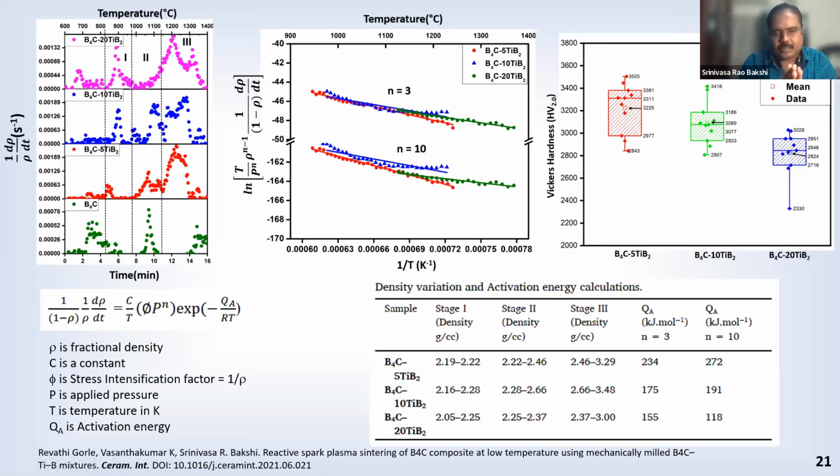So actually, the whole reaction happens in 4 seconds, and the melting happens, and then once the boride is formed, the boride has a melting point above 3200 degrees centigrade. So there is a transient liquefaction, and then instant solidification that is happening. This is what we believe.